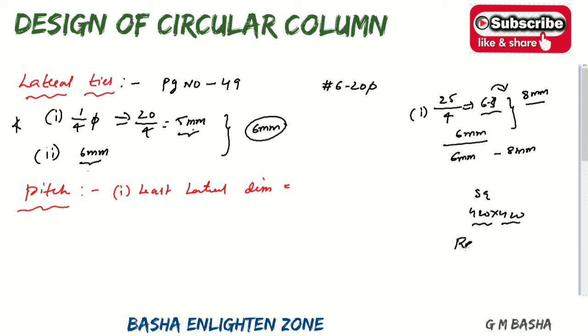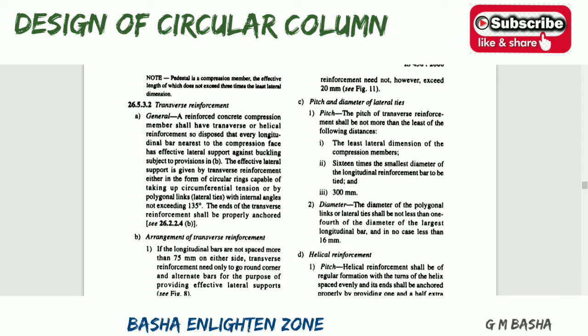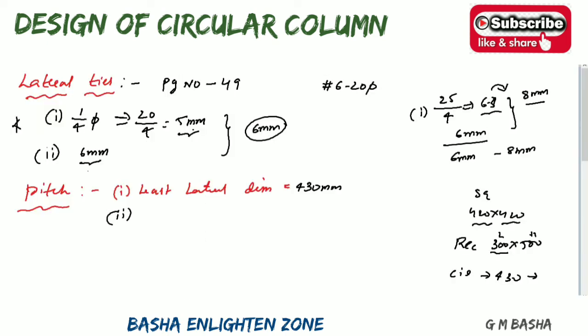If you have a rectangular column of 300 by 500, you get one least value and one higher value, so you choose the least value as 300 mm. But here we are solving a circular column of dia 430 mm, so there is only one dimension, which is both the least and the highest. Therefore we take 430 mm. The next condition is 16 times the smallest diameter of the longitudinal reinforcement, that is, 16 times the smallest diameter bar.